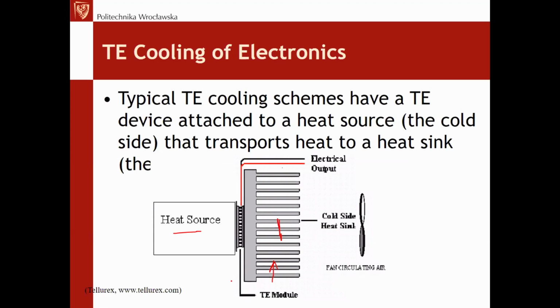Yeah, and then once again, the major advantage of the TE module compared to the standard use of the heatsink and the forced airflow element, is that with the TE module we can of course direct the heat from the heat source to the ambient, but by changing the polarity, we can reverse the heat flow, which means that the TE element or the Peltier element is the very standard component if we want to keep the temperature stable of some component, of some element.